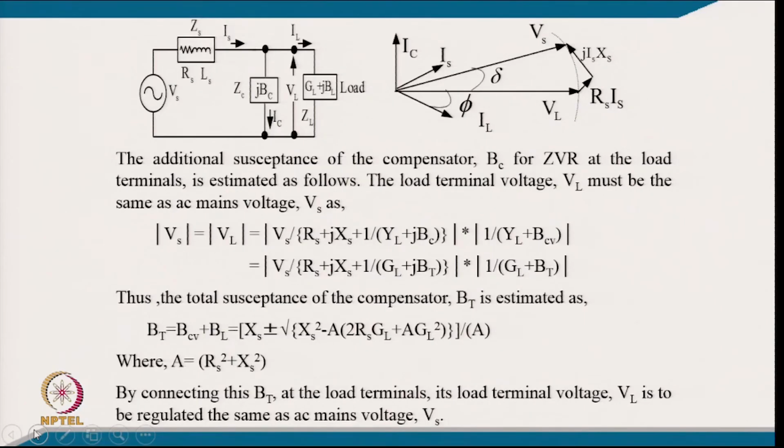That is the reason we have to go for this, and in substations we really use these capacitor panels. Now the phasor diagram corresponding to 0 voltage regulation, which we already discussed earlier: you are putting a compensator in parallel with the load, and we consider that VL equal to VS. If we put a compensator current a little higher, not only equivalent to the load, but compensating in a manner that the IS and RS drop, we draw a circle with the radius of VL over the center point, and this IS drop comes on this circle. So, this becomes VS. In this case VS will be equal to VL, because we are regulating the value of VL.